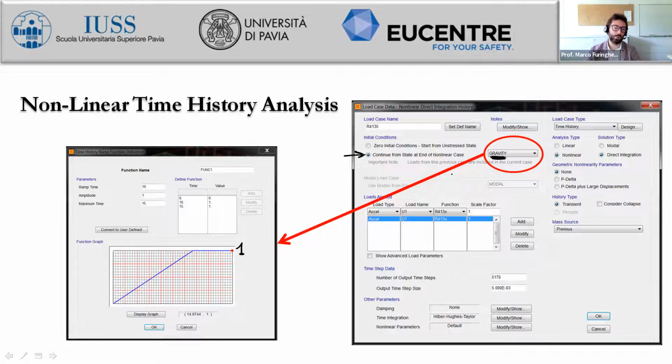For rubber bearings, which are linear devices, there is a linear, constant damping with the equivalent viscous damping ratio assumed in design. If we want to consider an additional damping, it should be limited to 2 to 5% maximum for seismically isolated structures.